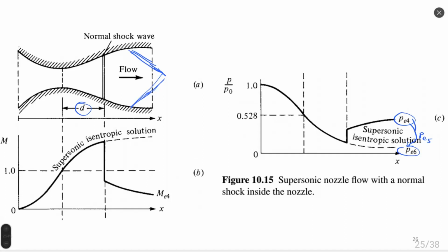It's an approximation, so we need several, three or four, iterations to calculate such a position of the normal shock wave. But it's possible to do analytically. We can determine the position of the normal shock wave inside the nozzle. We can calculate the flow distribution analytically, similar to figures B and C on this screen here. And I showed in my video how to calculate some specific points of these curves.